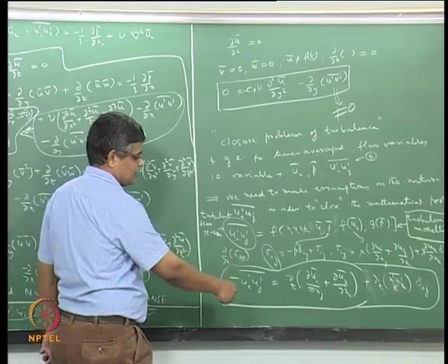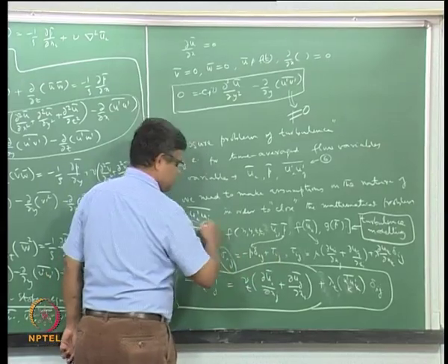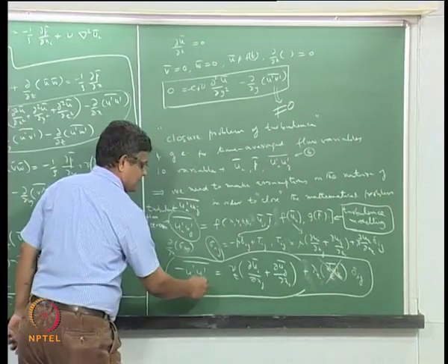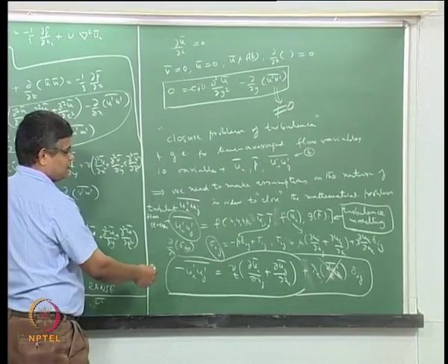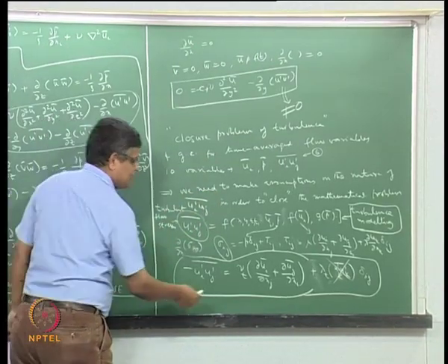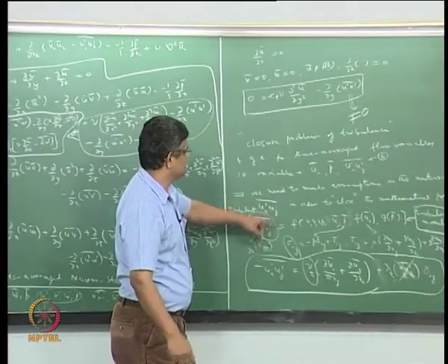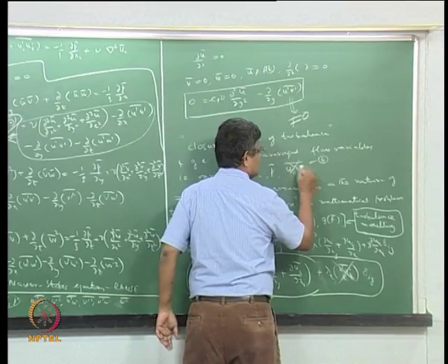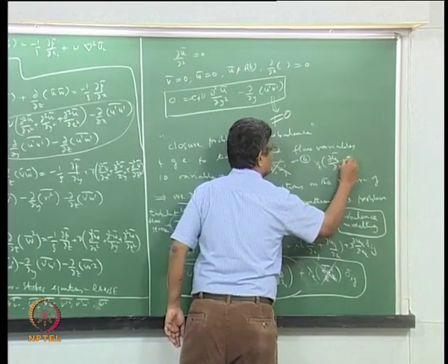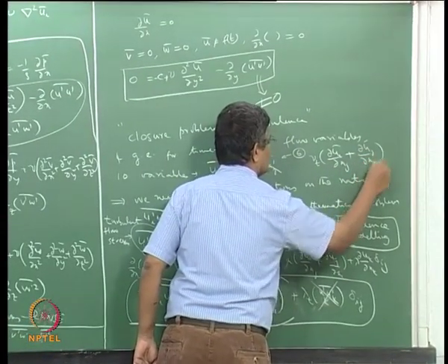And if we were to do that, then we can directly substitute this in these things and get rid of all these turbulent fluctuations. Okay, so if we neglect this for the time being and then we look at this, then the problem of turbulent closure can be completely overcome if we were able to specify this nu t, so that we can substitute this here and say that this whole thing is replaced by nu t times dou u i bar by dou x j plus dou u j bar by dou x i.